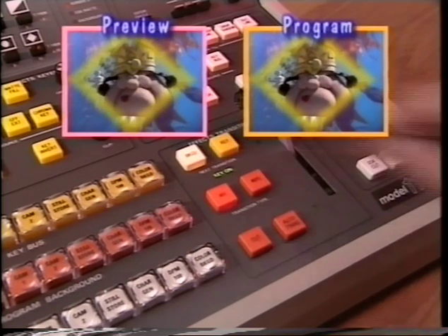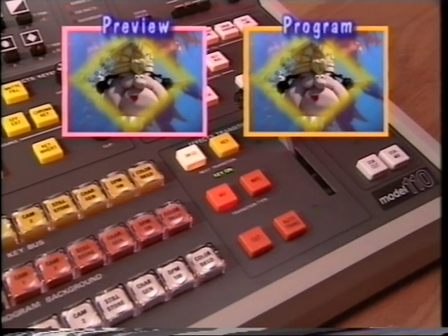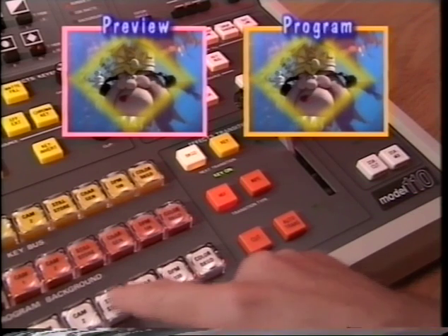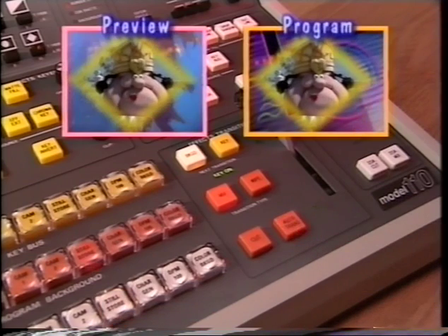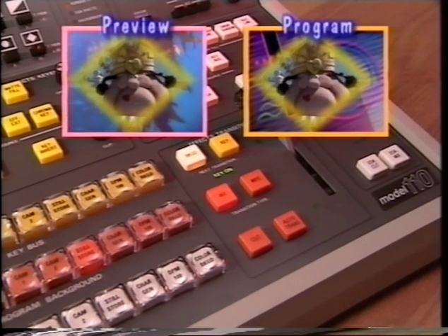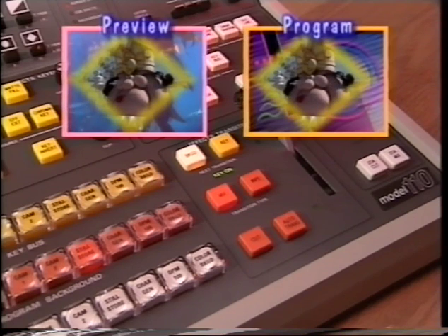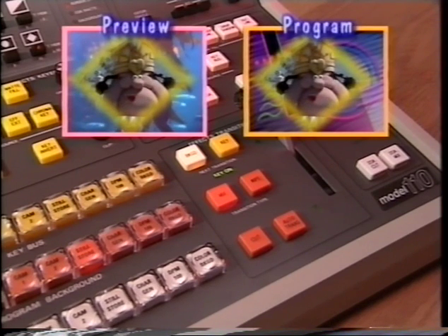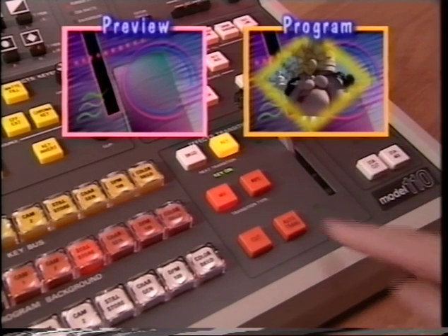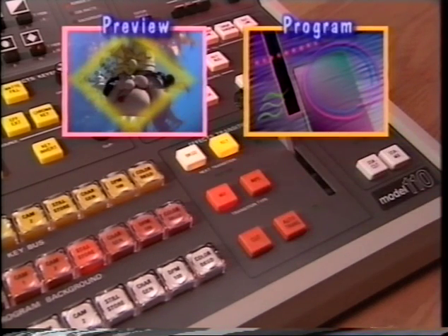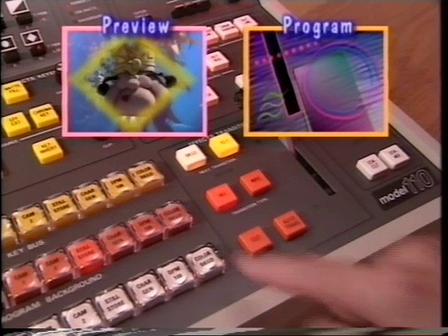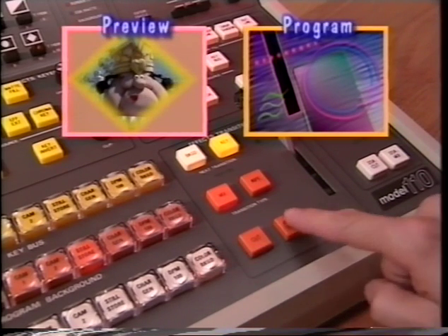To do this, select Background in the Effects Transition group. Select the new background on the preset background bus and perform the transition. You can also remove a preset pattern, either the pattern alone or both the pattern and the background. To remove the pattern alone, select Key and perform the transition. To remove both the background and the pattern, simultaneously select Key and Background. Then select a new background on the preset background bus and perform the transition.